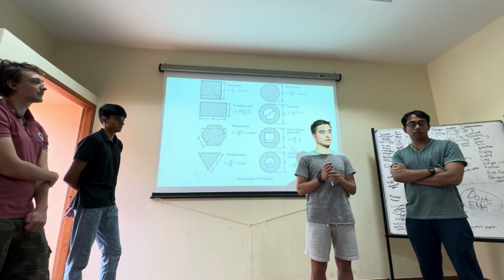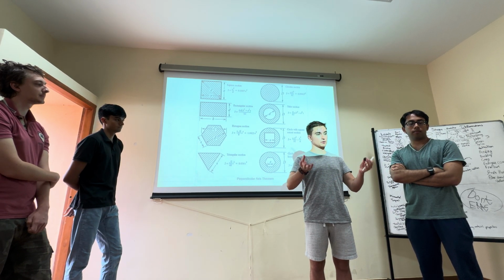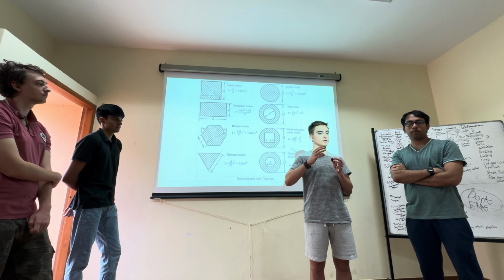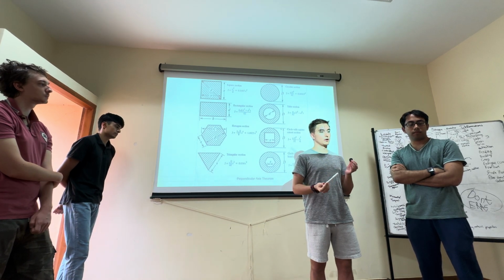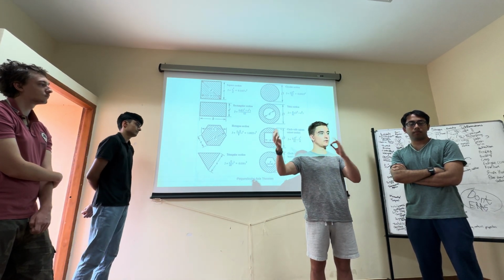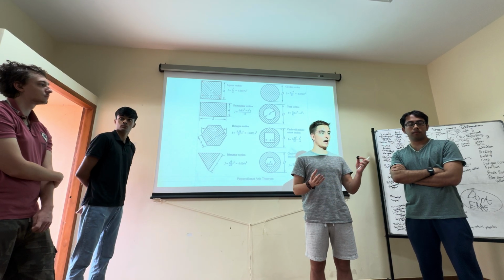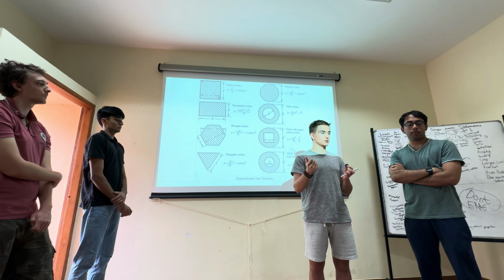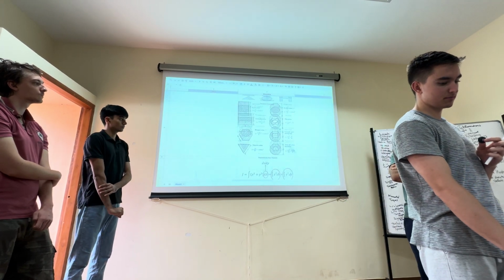And so that can be an important thing to consider when we talk about the different cross sections of what any sort of structure might look like, and what makes sense from the point of view of applying different moments or loads and where those have to come from. If you have a different value of J, or you move where that load is acting, that's of course going to affect how the moment is applied, and how that might affect failure stresses on that beam or on that part of the structure.